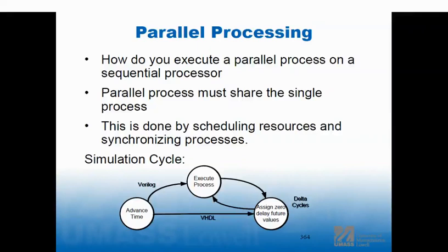Here's another example. This is important enough to dwell on. I build ring oscillators, and a ring oscillator is exactly what I just said. It's an odd number of inverters in a ring, and it oscillates. And it oscillates at a frequency that means something to me. I don't want to get too deep into it. But when I write them, I write it in RTL.